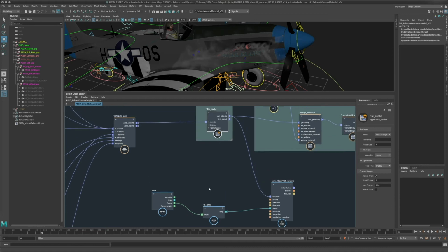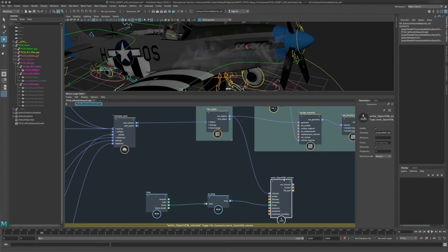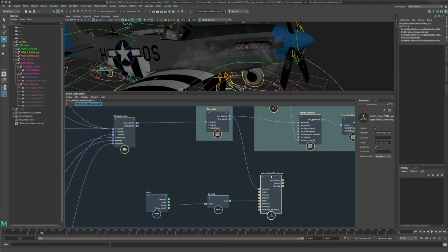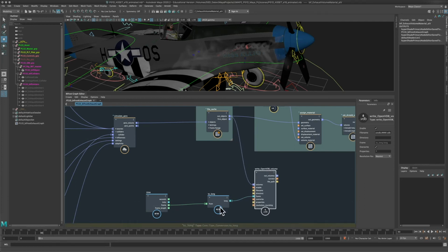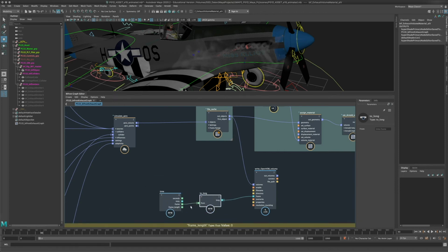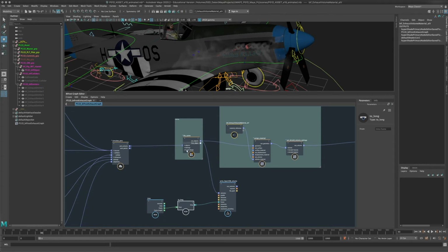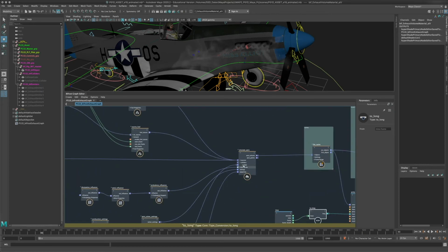So there are these little inconsistencies everywhere, and really the annoying thing is that time is a float. I have to convert time from float to long to put it into the right OpenVDB volume, and really that node should do that conversion internally by itself. There's really no reason that a frame gets produced by the actual time node that Bifrost uses as a float and then needs to be converted to a long for that. So yeah, there are some things that could be a little bit easier, but it works.